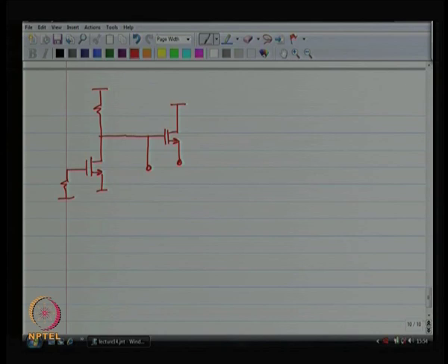So, it is like this. You remove all the capacitors, touch those two nodes with a multimeter and find out what is the resistance that you see. That is what you want to do.